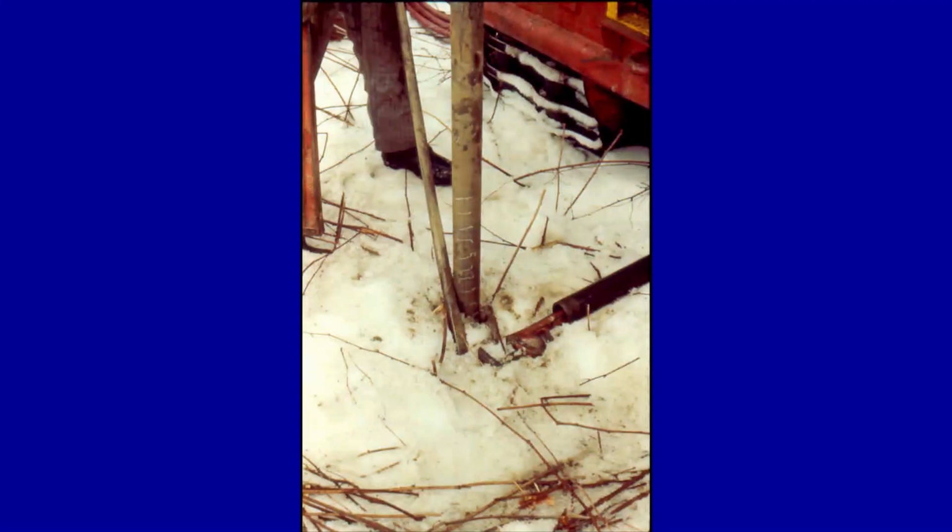This is approaching what we call refusal. Refusal may be either the underlying bedrock or dense glacial till. I have only four examples where till has ever been underlain by permeable sediments, and in those cases it has been a flow till. The till itself became saturated and flowed over on top of permeable sediments, and then a readvance of the glacier overlaid the till with sand and gravel, which is clean.